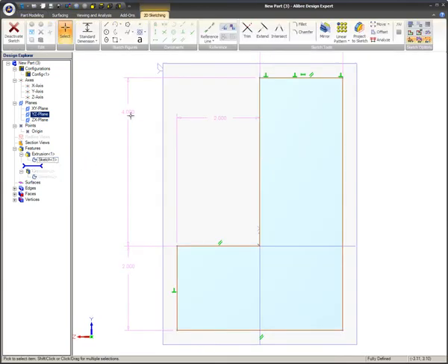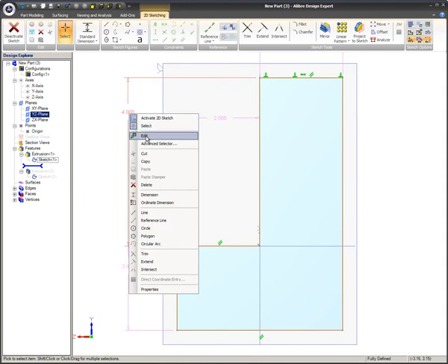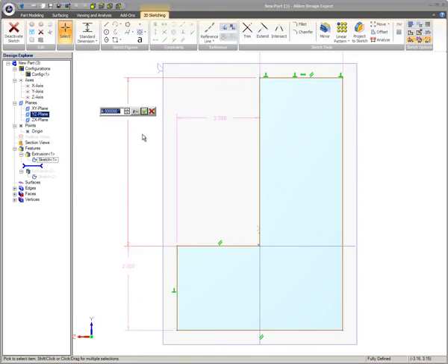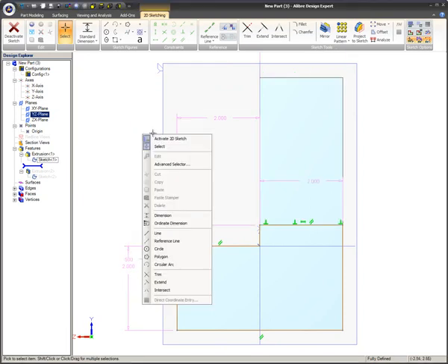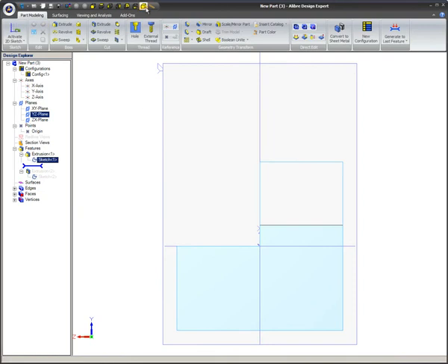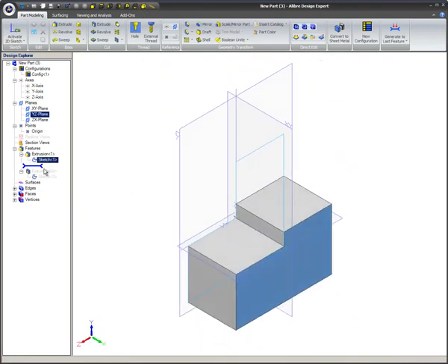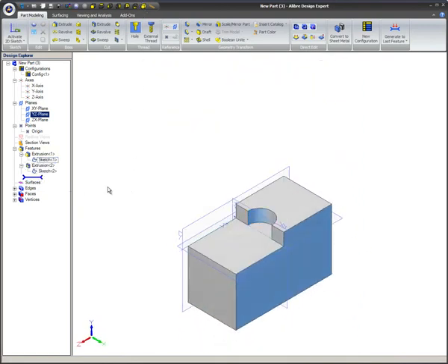When the height of the same section of the object is lowered to a 1/2 inch, the extruded cut continues to run from the top surface to the same lower surface. The height of the part is now irrelevant to the extrude cut. The sketch will always extrude to the surface. If you had used the To Distance parameter, the extrude cut would not always cut to the surface. Instead, the cut would have always extended to the distance specified in the distance section of the dialog box.